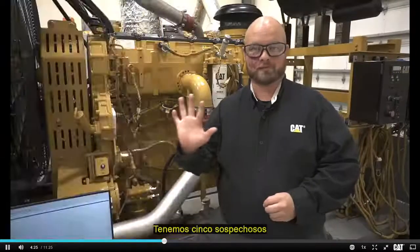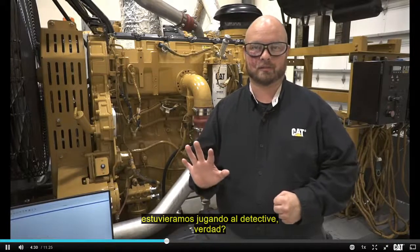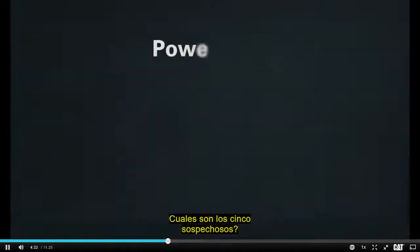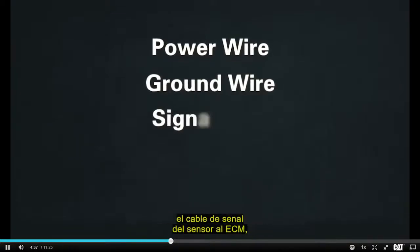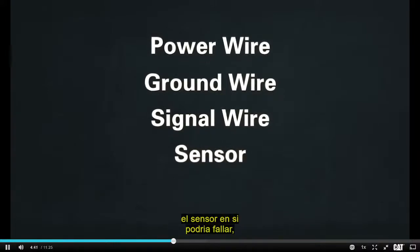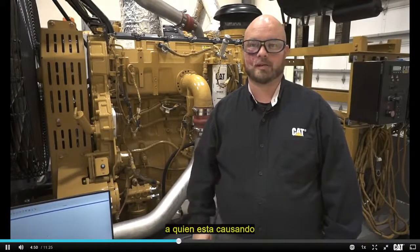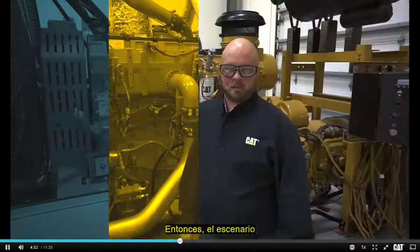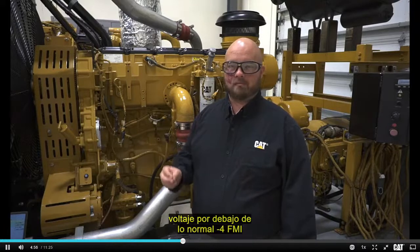We've got 5 suspects that could be the root cause of the problem. It's kind of like we're playing detective here. What are the 5 suspects? The power wire to the sensor, the ground wire to the sensor, the signal wire from the sensor to the ECM, the sensor itself could be failed, or the least likely, the ECM has failed. We're going to go through the troubleshooting steps that will lead us to what's causing our actual root problem.